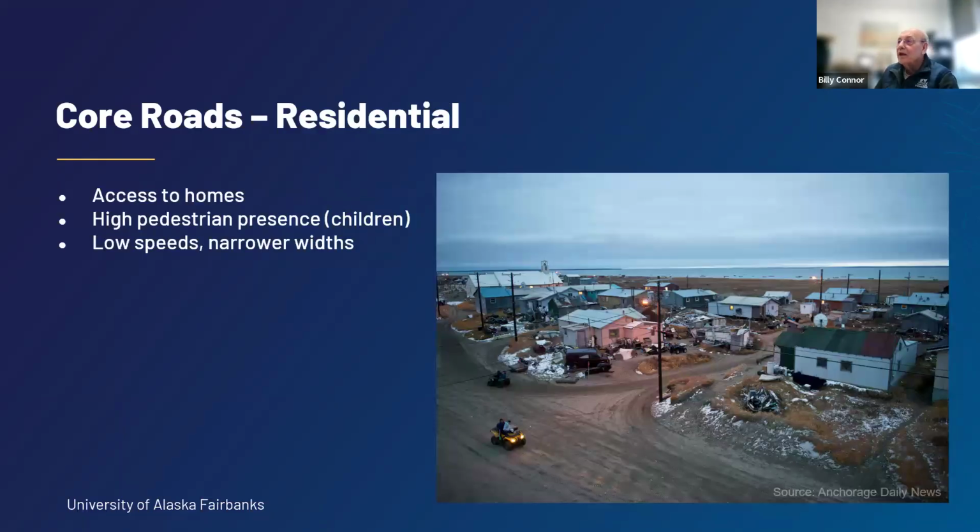Next. Okay. The residential streets, those are the ones that are gaining access to the homes. They have a very high pedestrian presence, often children playing in the streets. That becomes more or less their park where they play. They tend to be narrower and at a bit lower speeds.